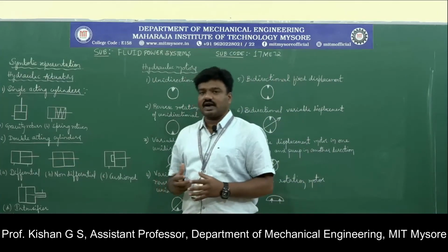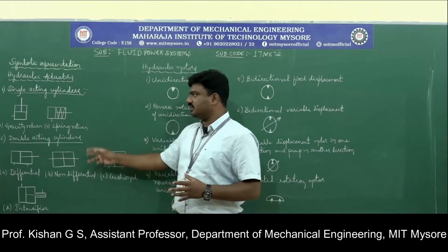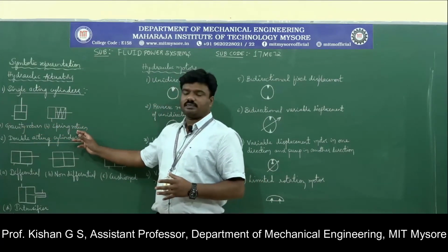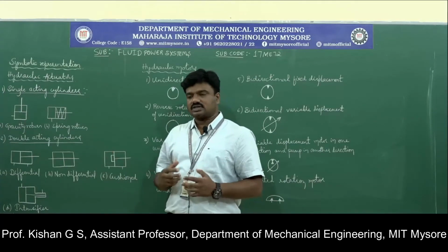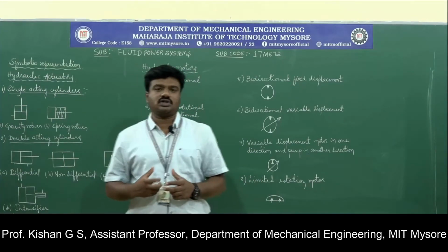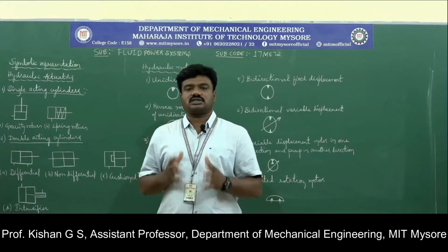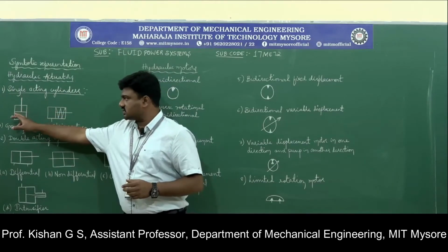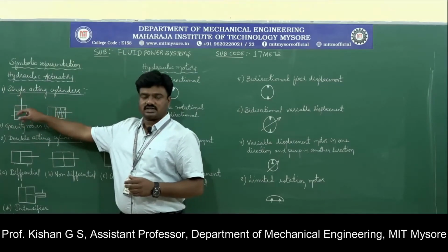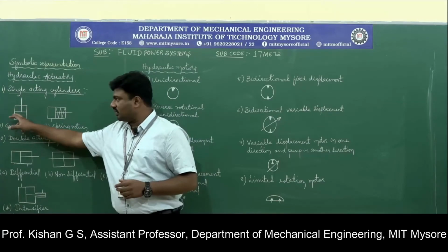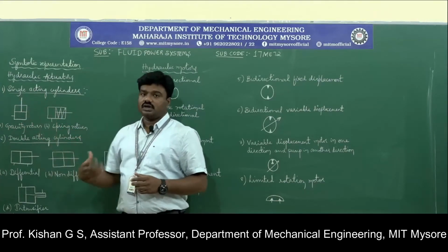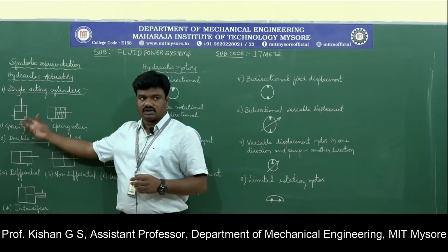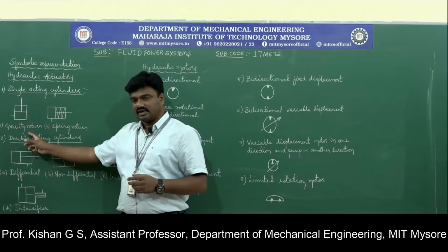So we have two types of hydraulic actuators, single acting and double acting. In case of single acting, we have gravity return type, spring return type and telescopic type. Telescopic doesn't have that much graphical representation because the entire construction itself is the graphical symbol. Here, this represents the piston and piston rod wherein the additional load will be carried, and we have only one port that results in the extension of the piston, whereas the retraction is basically due to the gravitational force or the dead weight of the piston. Hence it is gravity return type.